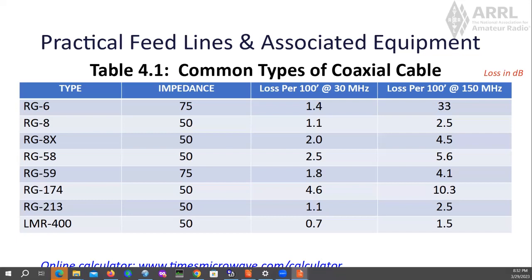Don't think that it's magic. Don't think that it is carved in stone. Just remember if they ask you something about figuring an antenna length, 468 is a good number to remember for taking the test. 234 is just half of that. That's your quarter wave length.